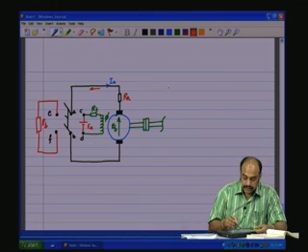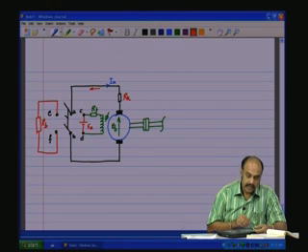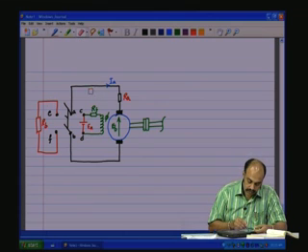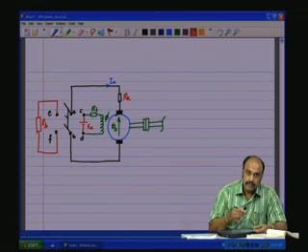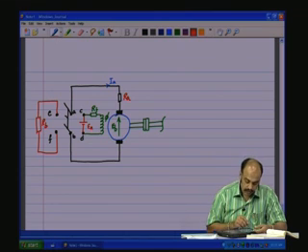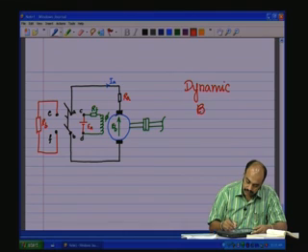Therefore, the energy stored in the inertia, instead of being dissipated in the mechanical friction, is going to be dissipated as electrical heat in the braking resistor RB shown here, due to the armature current now flowing through the resistor. This will bring down the speed pretty quickly, just like in a mechanical brake. This kind of braking is called dynamic braking.